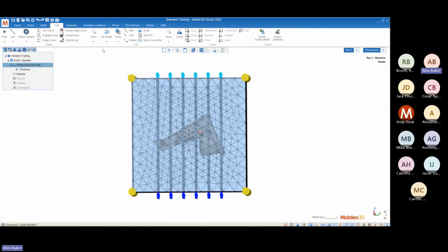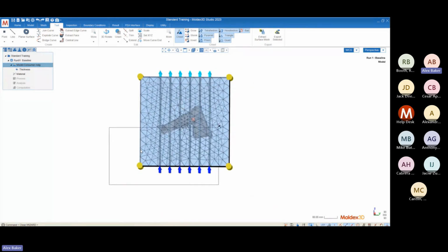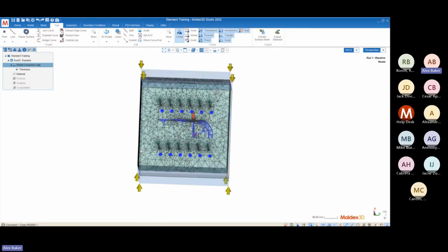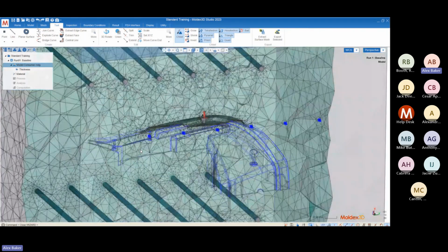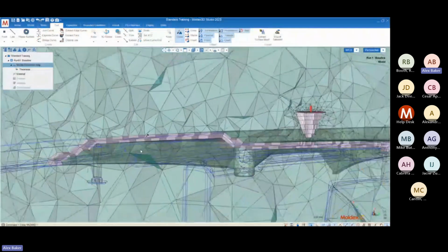You can see a bunch of line creation functions, surfaces, interactions, rotation functions, all those sorts of things. But over towards the right, there's a chisel function. I'm going to use the chisel function. The way that this function works is I'm going to left click and drag a box. Any element contained within that box is going to be temporarily hidden, and it allows me to see the styles of mesh that are created for each different part of my geometry.